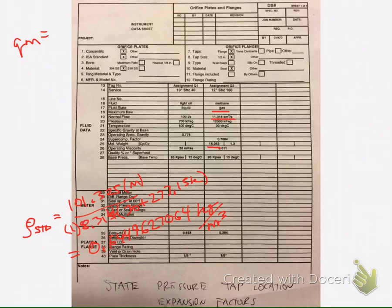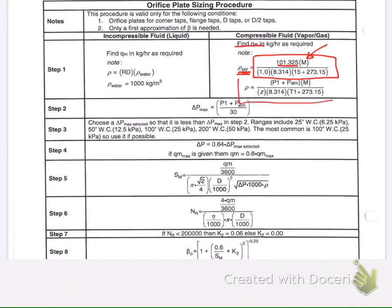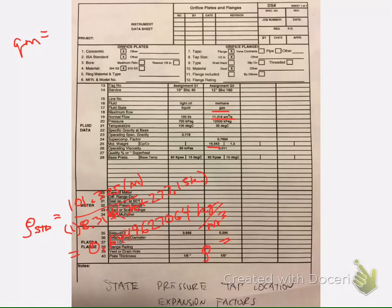So let's grab that as well. We need the absolute pressure times the molar mass times our Z at flowing conditions, which is given, and our temperature at flowing conditions. And I just realized we made a mistake. Uh-oh. Yes, this here should have been 15, not 30. So that's going to change this. Good thing I caught that now.